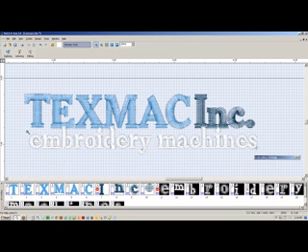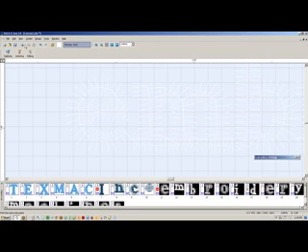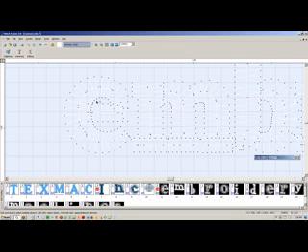So what we're going to look at here is the lettering. I'm going to get out of realistic view and show my stitch points and just press letter P. What you're trying to do is measure the distance between each stitch point and make sure that they are at least 1 block wide, ideally 1.5 blocks wide, and you can see that for the majority of these letters, these stem widths were okay. But there is a danger in this font.